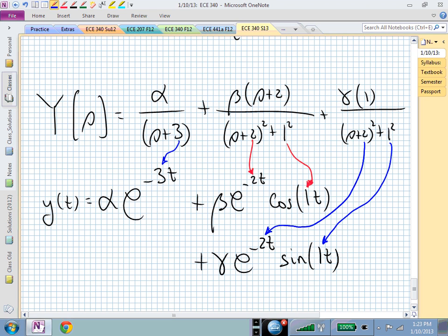How fine do I sample, and for how long? How long do I have to simulate this before it basically is gone? You could say, well, I can simulate that for 1,000,000 seconds. Yeah, you can, and it would be right, but then you wouldn't be able to hardly see your waveform because your axis is so long.